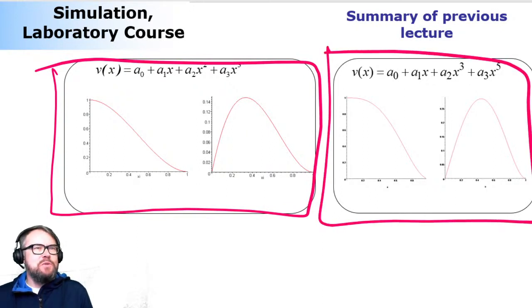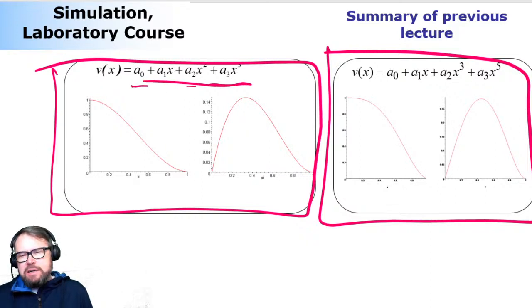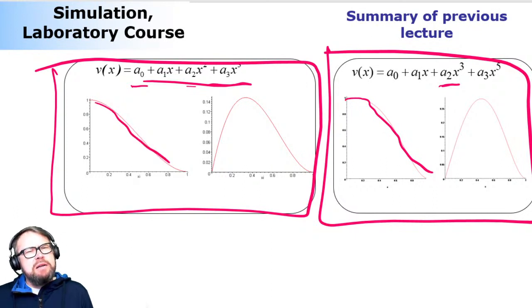But of course, you would like to know which one is better. Well, like I said earlier, to play safe, it may be a good idea to select the polynomials in order, like this. But some of the good performing elements are actually the elements where you don't select all the polynomials in order, but you are skipping some of the components and using the higher order polynomials. And obviously, this is affecting how the element can deform. Like you can see, this looks a little different than this one. So it may come with certain benefits.